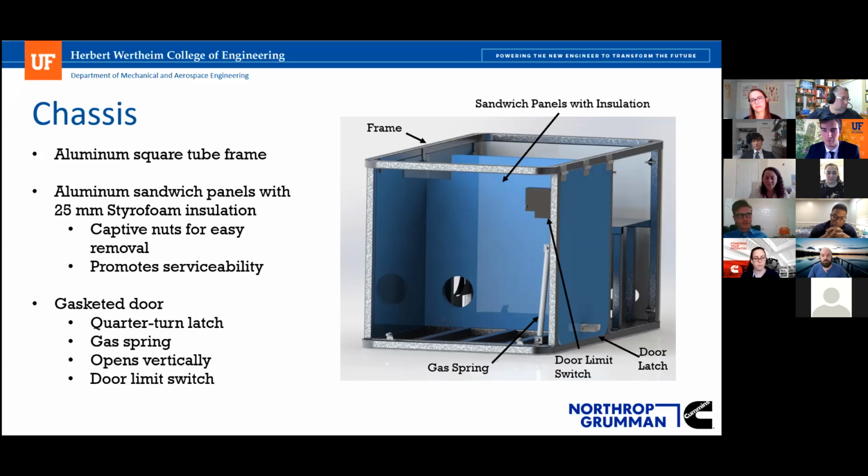The gas shock, I think, is rated for 20 pounds. We haven't done the kinematic analysis, based on over centering of the pin as you open the door and it swings back, of how exactly much force it would cost. The weight of the door, I don't have off the top of my head, but we feel that we could certainly, if we spend a little more time there, source a gas spring that works and is not too heavy to operate.